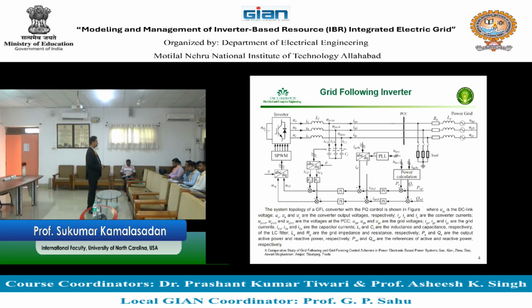Okay. So now you take the knowledge from the synchronous generator. If you want to control a 3-phase synchronous generator, you take the 3 phases, but the 3 phases are balanced. You take only 2 out of 3 by transforming from 3-phase to 2-phase. I think we discussed this some time ago. This transformation of 3-phase to 2-phase for control is called the DQ transformation, where you take a 3-phase ABC, convert that into a coordinate called alpha beta, and from alpha beta, convert that into a coordinate called DQ.